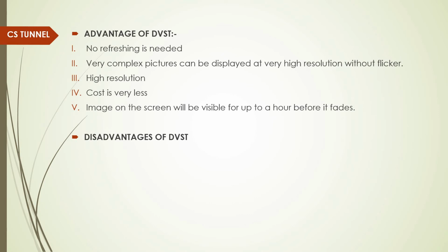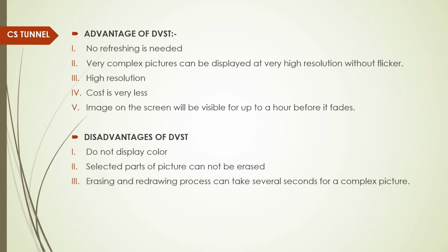Now moving on to the disadvantages of a DVST. It does not display color. Selected parts of a picture cannot be erased. Erasing and redrawing process can take several seconds for a complex picture.